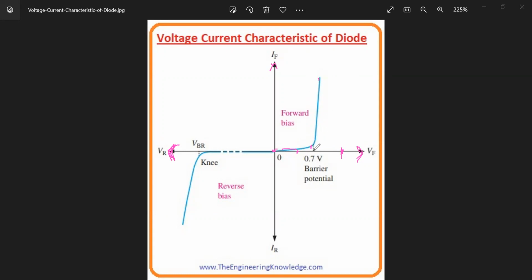So you need to make sure that this diode only gets a voltage within a certain level, let's say up to 0.75 or 0.8 volts, because it can't handle more. If you provide more, it's definitely going to burn out.